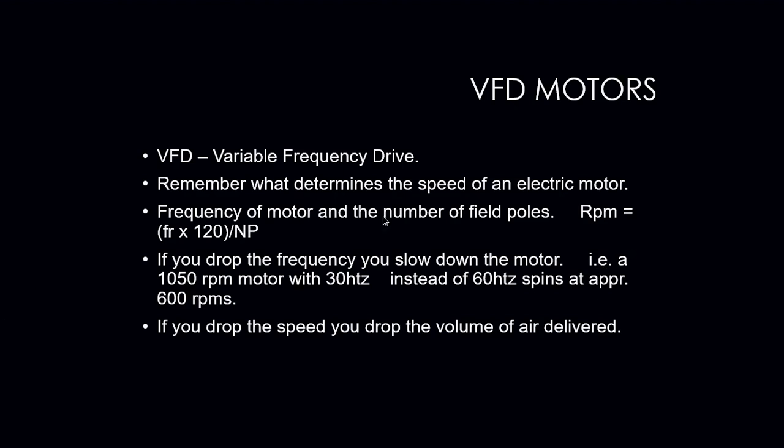With variable frequency drives, basically how these work is if we drop the frequency on a motor, we can slow it down. Okay, we can take a motor that's spinning at 3450 RPMs at full speed, and if we slow the frequency down to say about 30 hertz, we are now able to make that motor run at about 1050 RPMs. Okay, so these have nice characteristics. In fact, I think they're great. But we have to understand how they actually work.